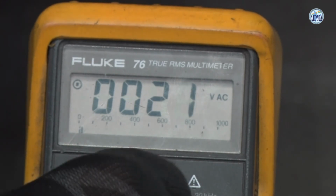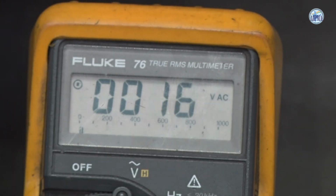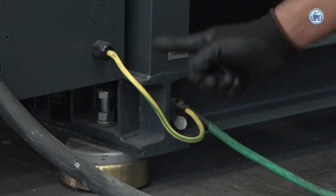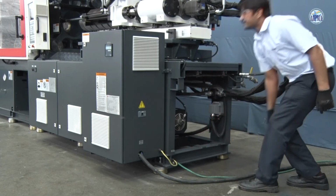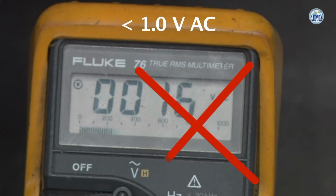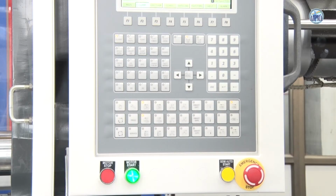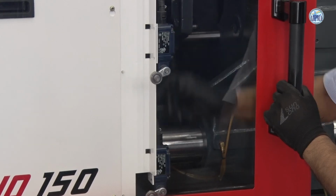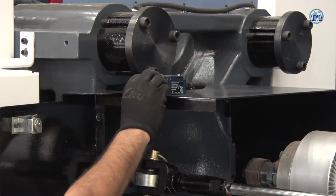plus or minus 5%. Check proper earthing connections on machines. Ensure the voltage between neutral and earthing must be below 1 volt. Perform all the safety checks, like ensure operation of emergency push button, front gates and rear guards interlocks for proper operation.